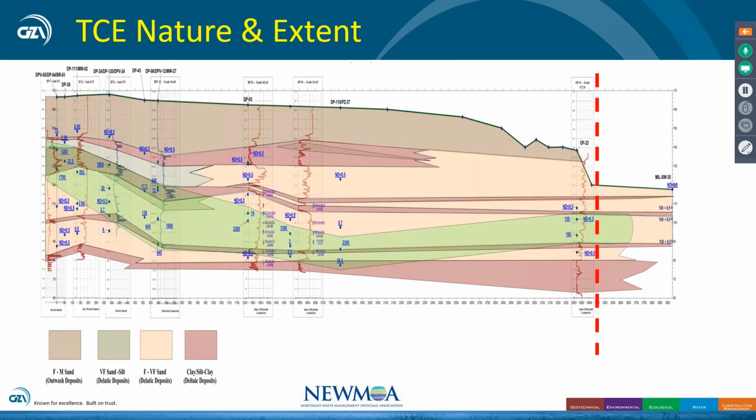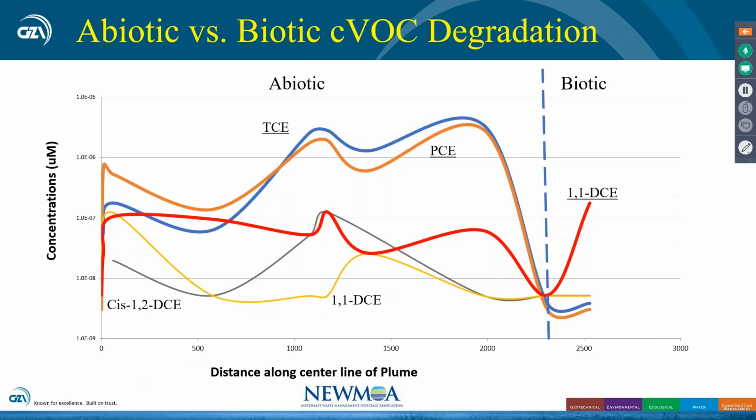And again, going back into that conceptual site model, where we have high concentrations, the green is the hex chrome plume mixed with VOCs. We have our dividing line where Mother Nature is taking hold. And what we're trying to do is just reduce this mass up here, shrink the plume, and then let the rest of the system go. Therefore, not treating 690 acres, only treating a portion of the site to reduce mass.